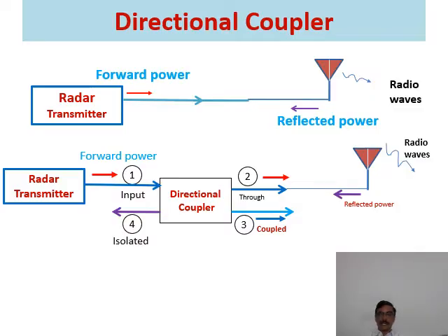We'll discuss more in detail about these directional coupler connections. And here at port 3, I will connect the spectrum analyzer or power meter, etc., for analyzing the signal or to get VSWR or reflected power, incident power if there are.